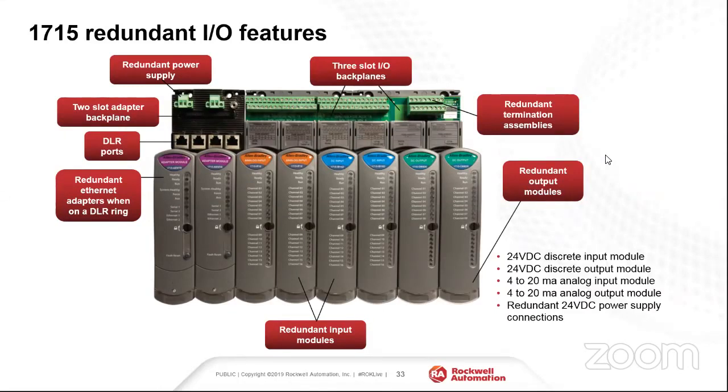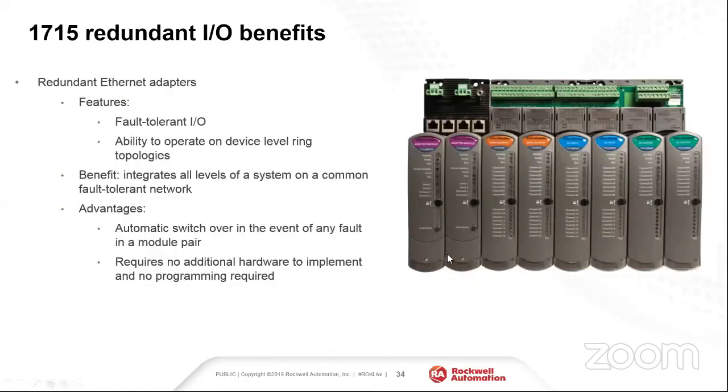And in simple aspects, if you guys want more information, the slide or the IO cards themselves can go up to 24 IO cards. So we have the adapters that are there. And as we bring everything in, typically we see this for your critical systems that require redundant IO, or even a process safety solution that would require up to a SIL2 implementation. We do this with ControlLogix, either a fault tolerant with a redundant controller, or even a fail safe with just a single ControlLogix adapter going to EtherNet through this connection.